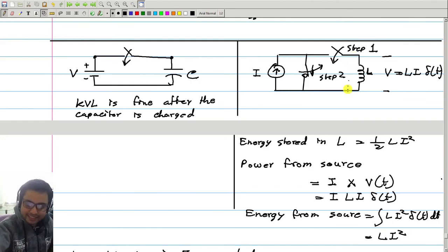And also in this case, one very interesting thing you observe: like here there is an inductance which we are ignoring, here there is a capacitance which we are ignoring. Where is that capacitance coming from? See, even for a brief moment, we need a voltage to appear across this inductor. Otherwise current cannot increase. So we need voltage. But how can we get voltage? Voltage can come only if there are some charges or accumulation of charges. So definitely for a brief moment there will be an accumulation of positive charge here and negative charge here.